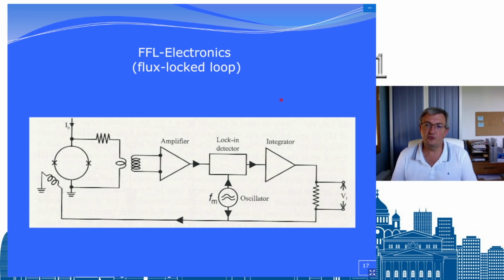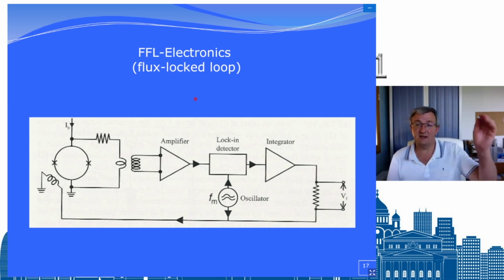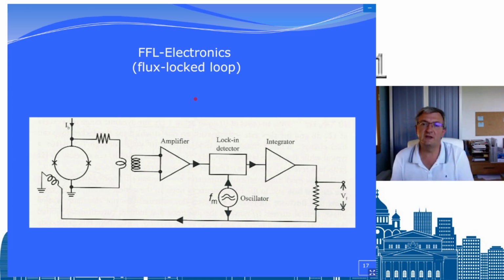And to use it in a simple way, you bias in current, and then you have a variation of voltage. If you leave the SQUID loose, it will be complicated to manage because it won't be accurate enough. So the way we do that in electronics, if you want a good measurement, is you need to constrain your system, and you make a phase lock loop to keep the voltage constant, and you measure the reaction. Here, you measure the current in the feedback loop, which gives the information about the voltage.